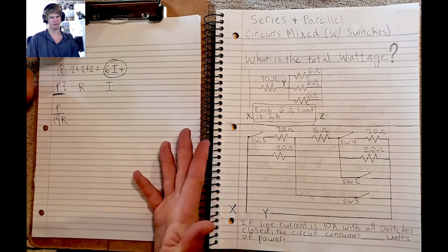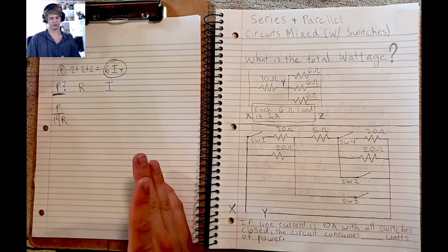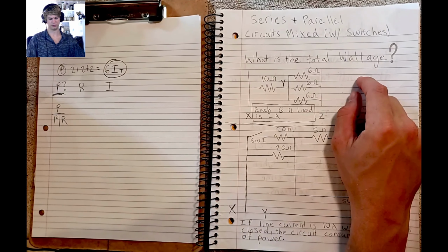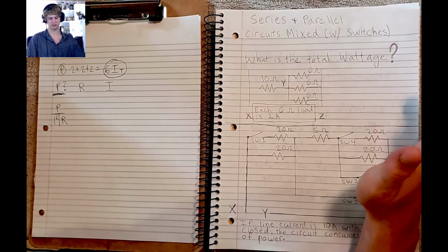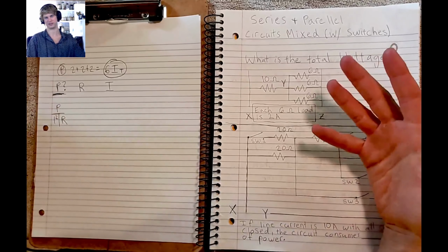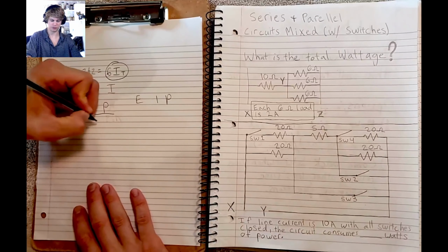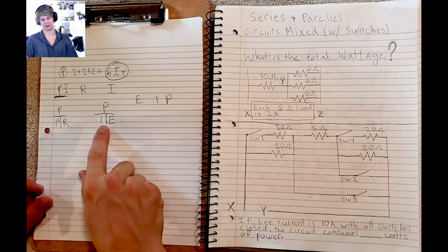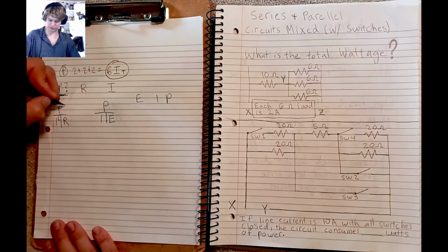The only problem is sometimes we seem to be running into some problems when we do the resistance total. So when you stop and think, okay, we're solving for wattage, would this be a good time to do the resistance total? Maybe we could find a formula that doesn't include the resistances, but still includes current to get power. And of course, process of elimination, that would have to be voltage. Okay, so the formula has E, I, and P, and of course that would just be the simple formula, P = I E. "Pie" is a funny way to remember it, but the better way to remember is that it's current times volts equals watts.